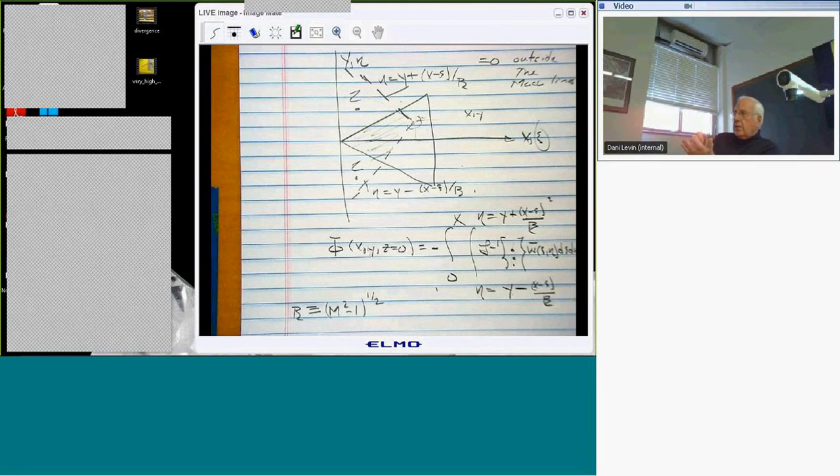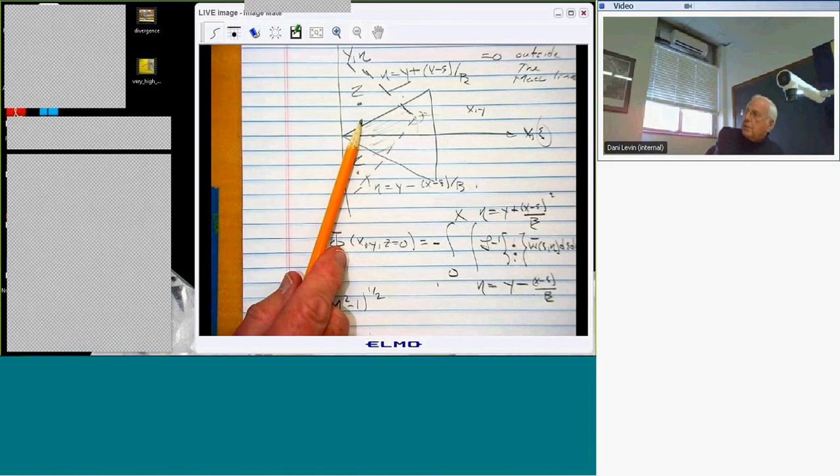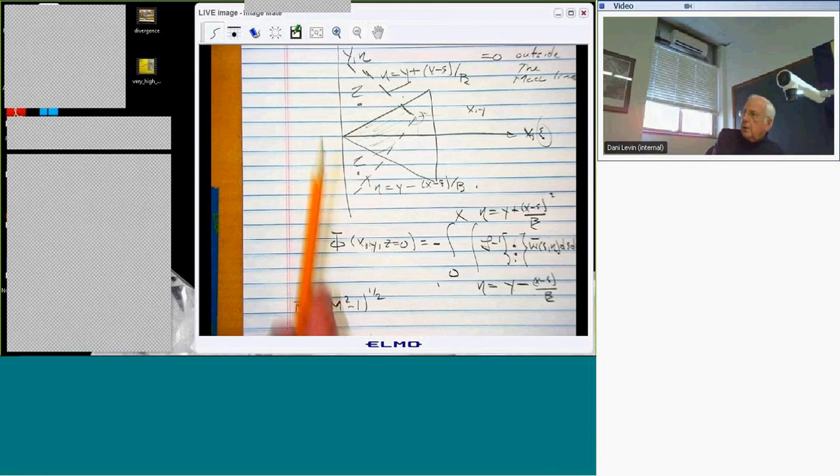It's sucking up on the top if I'm at a positive angle of attack, and it's pressing up on the bottom, right? But out here in the fluid, there's no wing to support a pressure jump, so the pressure must be continuous. It also must be anti-symmetric in that what happens plus, what happens minus must be equal and opposite. Therefore, the only way that can happen is if the pressure perturbation is 0 off the wing, which also, it turns out, from Bernoulli's equation, implies that the velocity potential must be 0 off the wing as well.